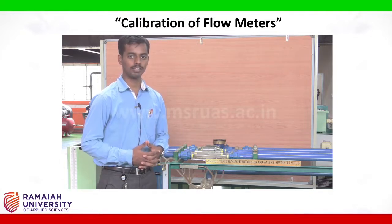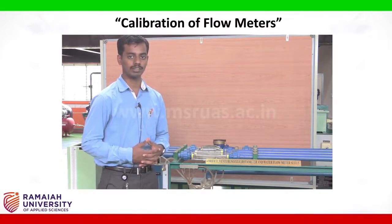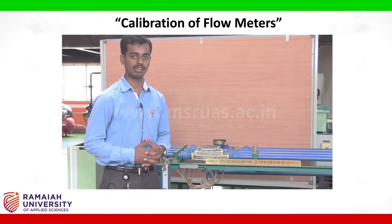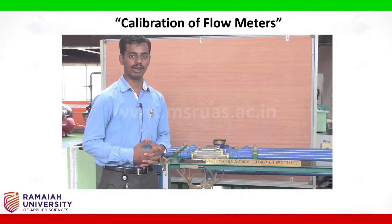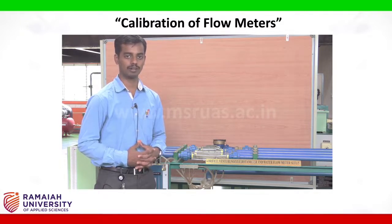We shall observe that there will be some error between the flow rate readings on the rotameter and the nozzle meter. We shall calculate the errors and then finally calculate the correction factor which has to be adopted for the nozzle meter, which can be calibrated against the rotameter. We must ensure that the values on the rotameter are taken as the calibrated values of the rotameter, which was done against the venturi meter. Once all the readings are taken, we shall stop the pump, and that concludes the experiment.